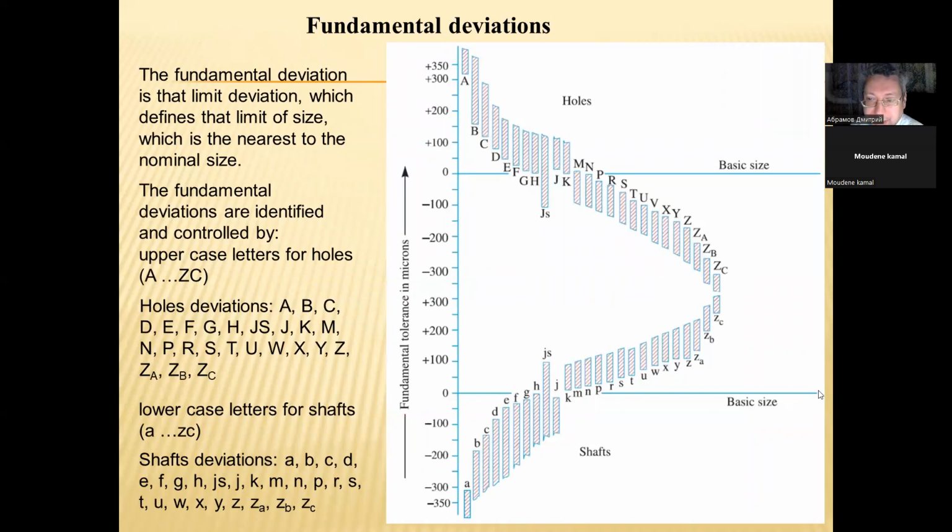Basic size: fundamental deviations for shafts are small letters, and fundamental deviations for holes are big letters of the Latin alphabet. The fundamental deviation is that limit deviation which defines that limit of size which is the nearest to the nominal size.